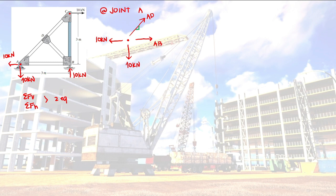This is 3, 3. So, we can say this is 1, 1, square root of 2. So, our component here would become 1 divided by square root of 2 AD. And this one also, this would be 1 over square root of 2 AD. After the components, we can now do summation forces, vertical and horizontal.